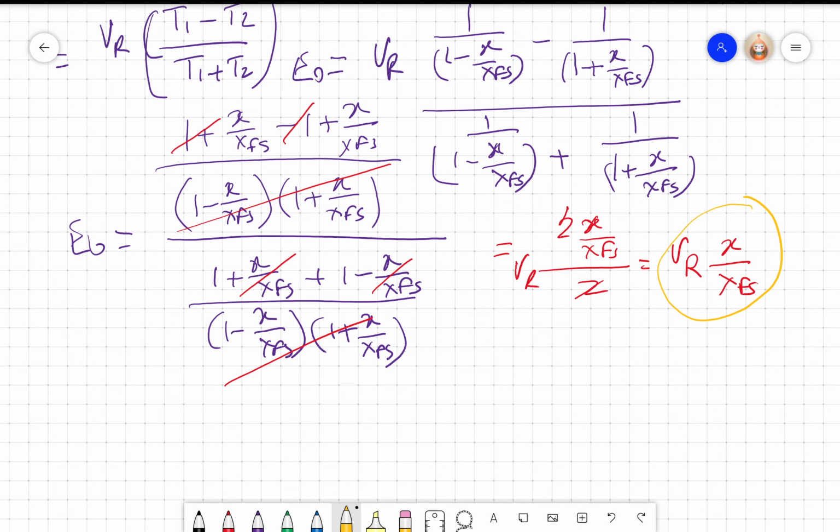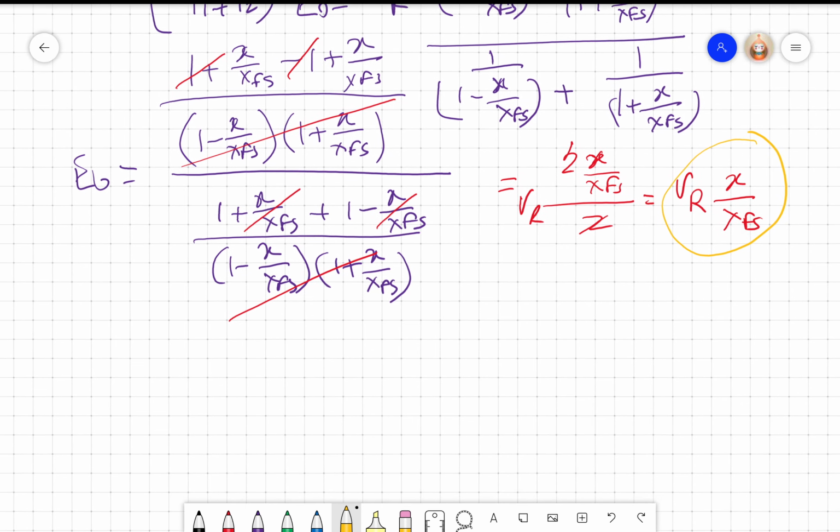So by using the relaxation oscillator circuit with totally 6 switches, one op-amp comparator and one op-amp integrator, we can get an output which is directly proportional to x from a floating resistive displacement transducer.